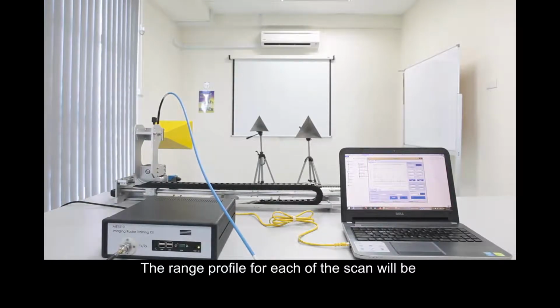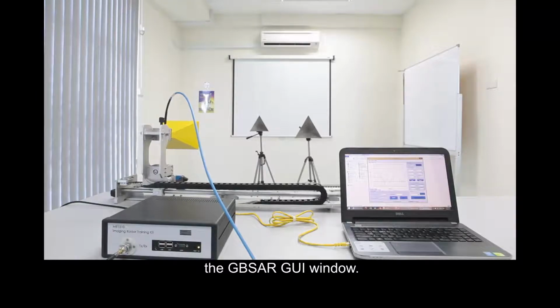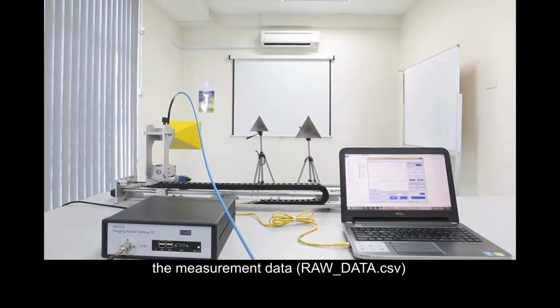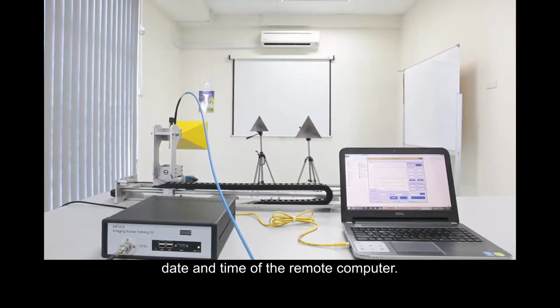button. The range profile for each of the scan will be recorded and displayed in the GBSAR GUI window. Once the scanning process is completed, the measurement data will be saved in the subfolders, with the naming format based on the local date and time of the remote computer.